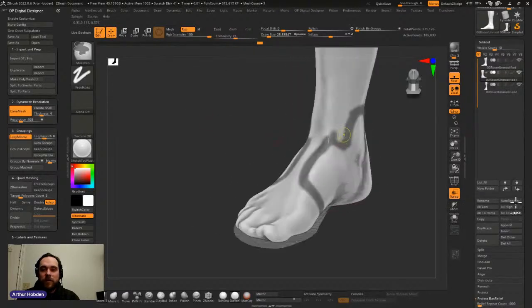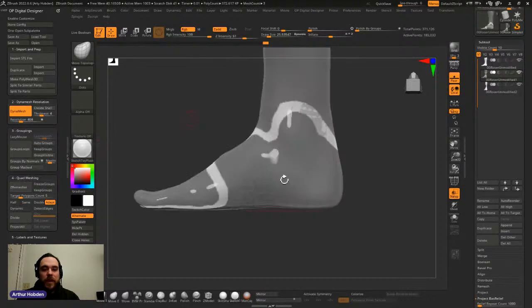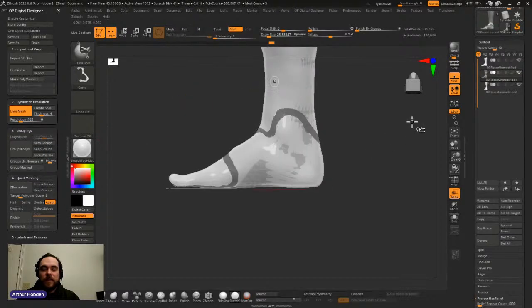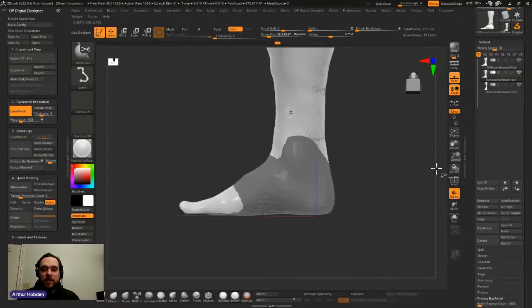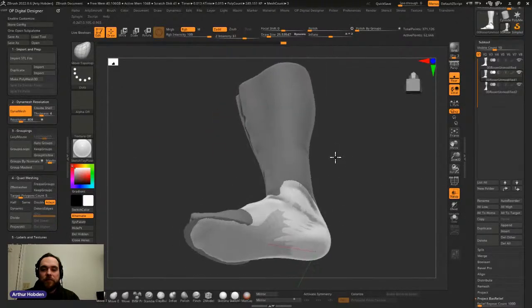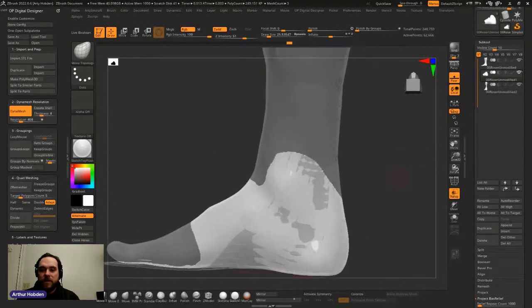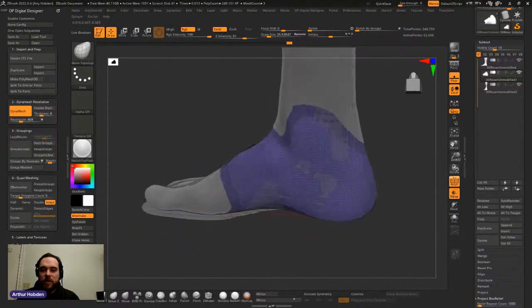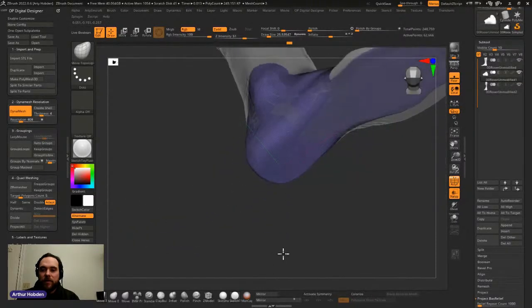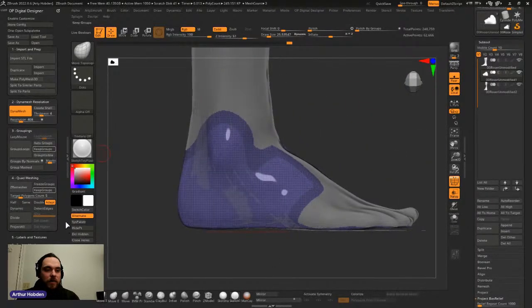So we are going to create a group from the masked area, clear that mask, select the other group, auto group those pieces so that we can select everything else but that, and delete hidden. So we now have a copy of this mesh as well. We've got a trim group as well as just a regular group throughout. Let's go ahead and quad mesh this back to something that's much more usable.